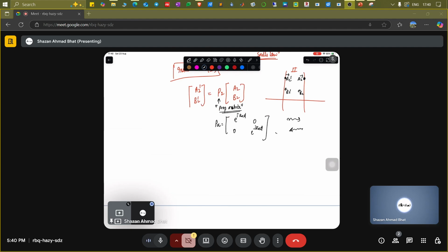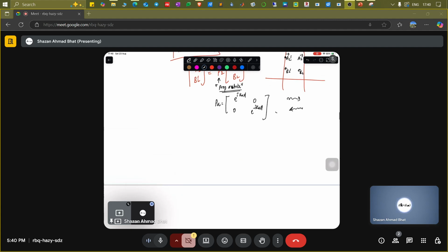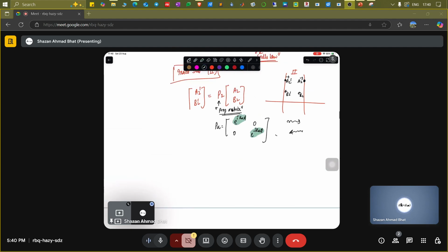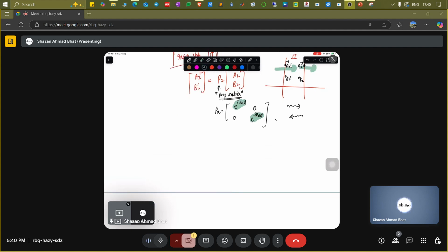It can also have a reflected component, so that is why this propagation matrix looks like this. This denotes that there is a certain phase vector associated with it. The wave cannot just go from this end to this end and come back here. It is having a certain phase vector associated with it. It's almost just like an electron. This phase vector also comes in electrons from the periodicity. And this d is here the thickness of the slab.